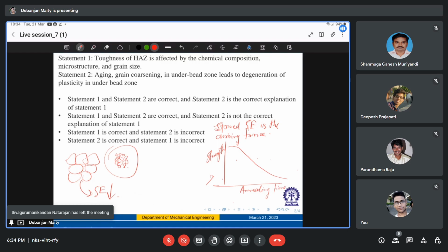So, as recrystallization happens, the extent of grain growth also increases with increase in annealing temperature. Here I'm not drawing anything. This is common sense, right? If initially you have some smaller grains, then because of heating you get fresh grains produced, which are initially undeformed, strain-free grains, and with time they will start to grow, which is called grain growth, right?